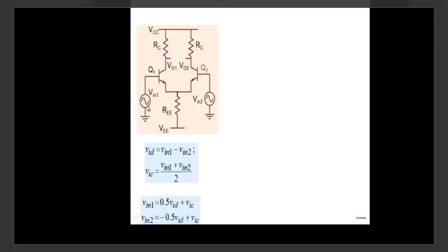So in differential pairs, we specifically make a distinction that we are doing a bias point analysis where we remove the sources in the sense that we make it ground. That's bias point analysis. And then we do small signal. The small signal can be DC, AC, whatever it is. So don't say DC analysis and AC analysis. That's not correct here.